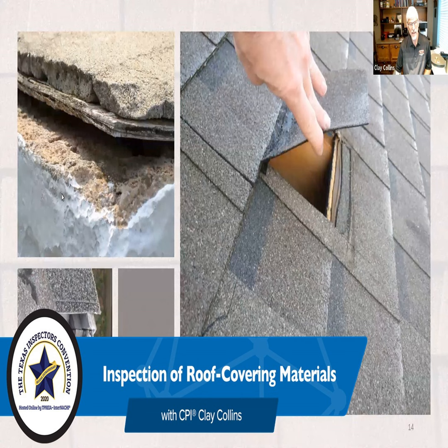What I see frequently is when there's a measurement problem and the deck joint does not line up over a rafter, they nail a board alongside it. In this case, I have no clue why they did this, but instead of nailing into the rafter, they nailed into the roof deck. That's a big oops. Fasteners alone don't keep the shingles down. A starter course.